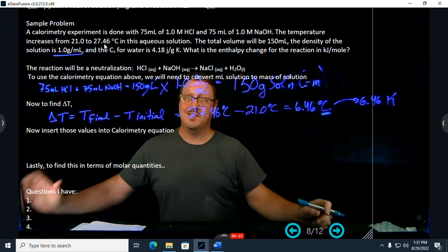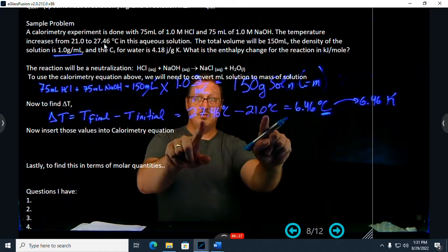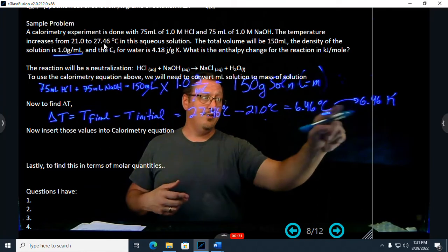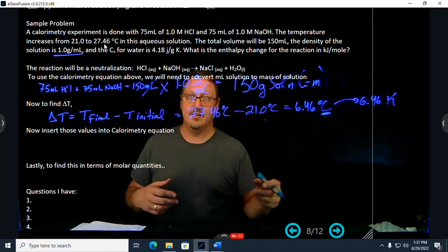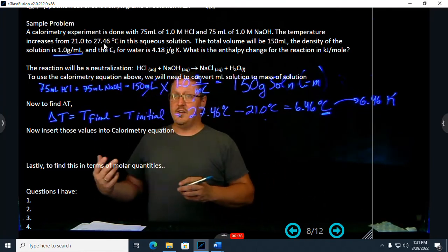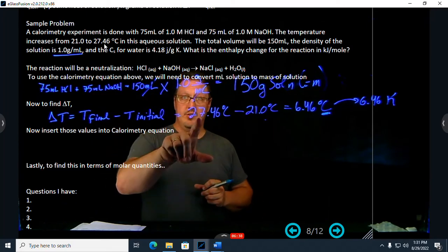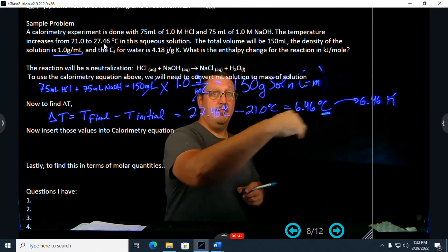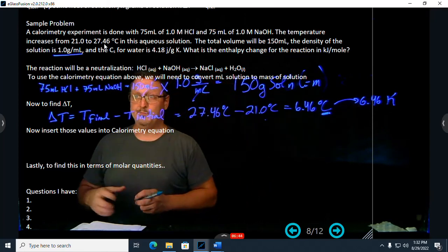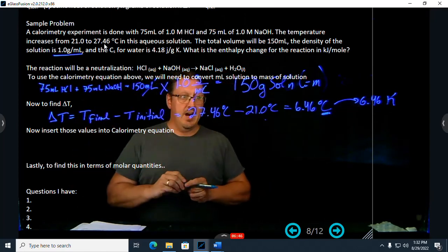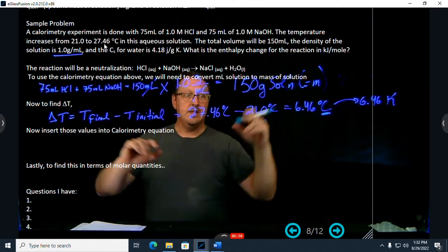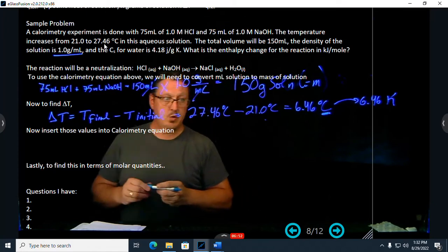Okay, because this is a magnitude. This is a subtraction between the two. And because we're subtracting those two values, I don't need to convert it. It's just K. Just do the math on it. If I wanted to convert it to Kelvin first, I could convert that to Kelvin, subtract that converted from Kelvin, and that would give me the same value as the 6.46 K. So there we go. Now we have our T final and we have our mass.